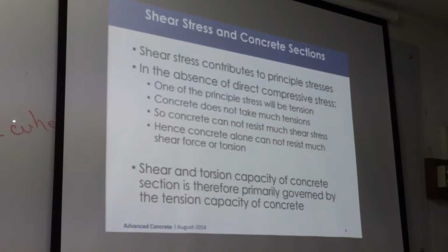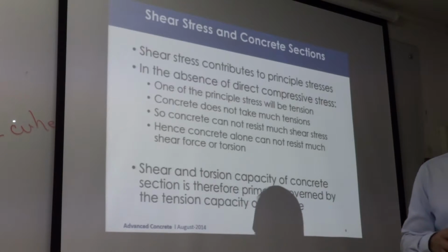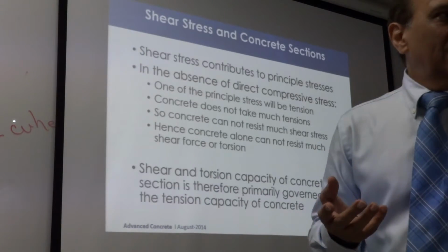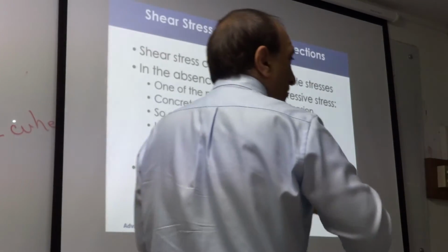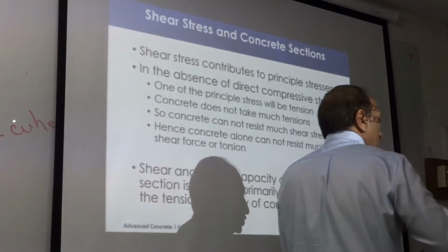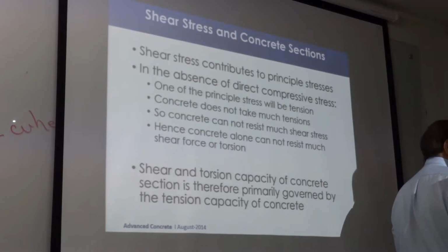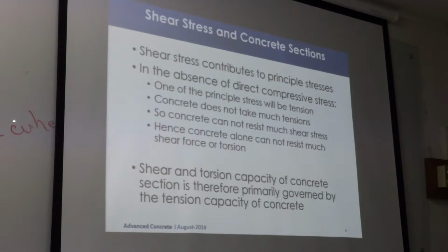Correct? Same is the case if you have all of that as shear, nothing is left for bending. So it's a transformation between shear and bending stresses. And some must always remain the same, which is the principal value, the maximum value of the material, right? So that's why there is a circle of the stress.